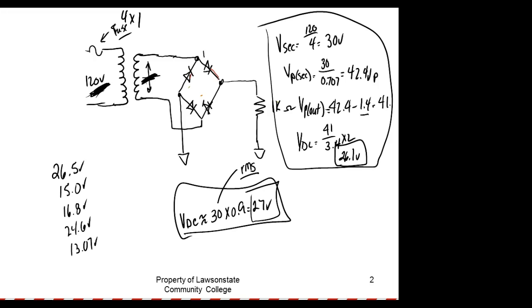So our resistors have tolerances, our diodes have tolerances. They usually don't give plus or minus, they'll give you a minimum and a maximum. When you look at a lot of these data sheets, what are they telling you? They're telling you the tolerance, which means it's going to be somewhere, but it probably will never be the maximum and probably never the minimum. It should operate somewhere between. We have a rating for a transistor, beta, which is the gain of the thing. The minimum is like 30, and the maximum is like 110. So we're talking about a huge tolerance, right?